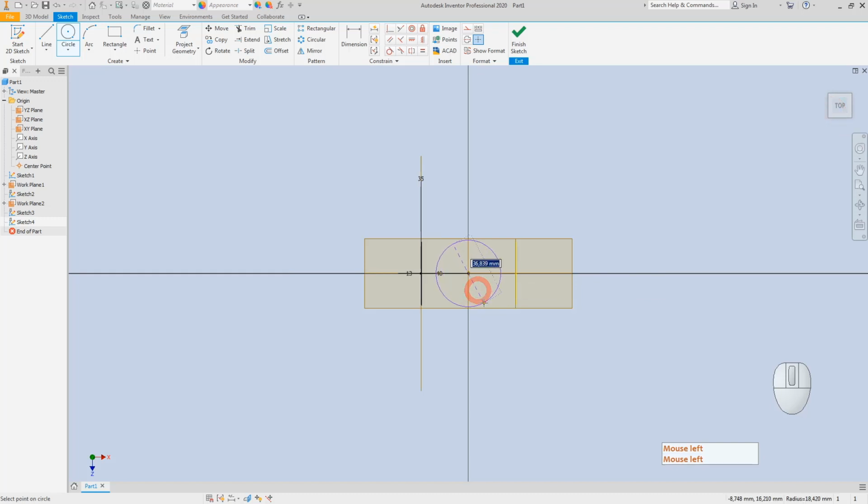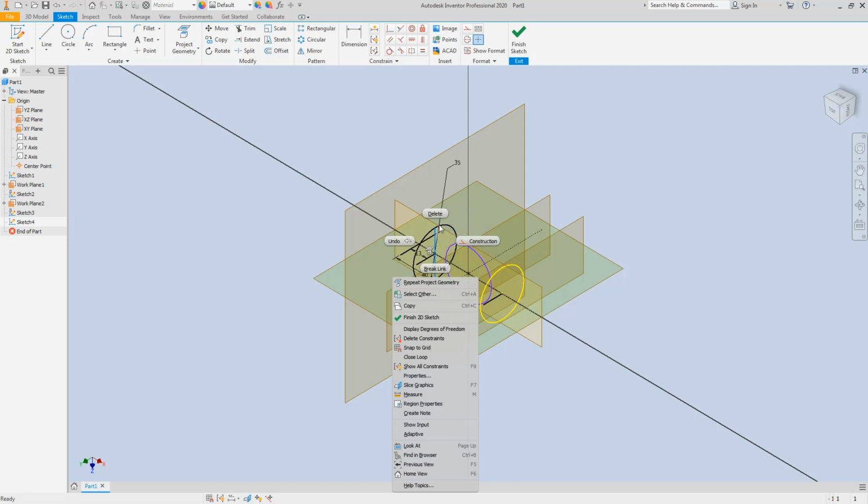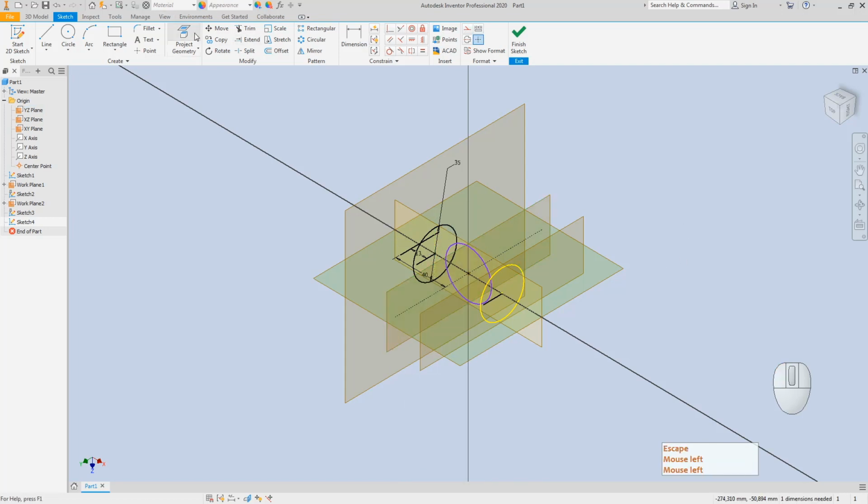We first create the circle, then get the geometries from the end sections of our objects. Then we will just create the lines starting from those objects, and we will make them tangent to the curve or circle which we have created at the midpoint.